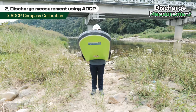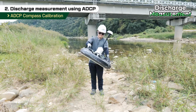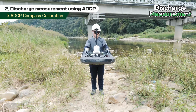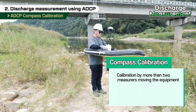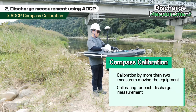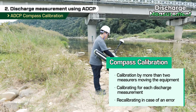You should calibrate the ADCP equipment for accurate measurement. This is because the intensity of the Earth's magnetic field varies from place to place, which can affect the internal compass. Compass calibration requires that more than 2 people calibrate it by moving the equipment for each discharge measurement, and if an error occurs, recalibration should be carried out.